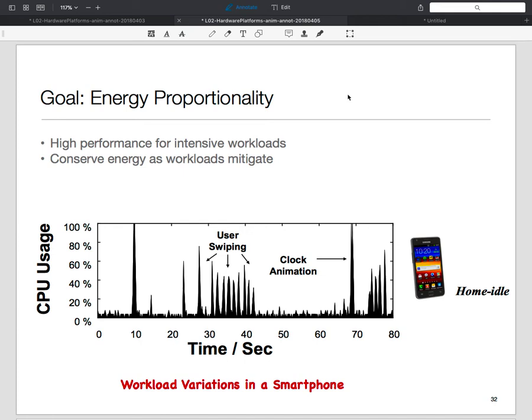For this, would the only way to make it back up be via some kind of hardware interrupt? Like a press button? Or a timer. Internal timer. So you tell the timer, wake me up. But the timer also sends a signal, a hardware signal. Okay. So basically, most of the chip is put to sleep, and there is some timer or autonomous chip still running. That's the one.